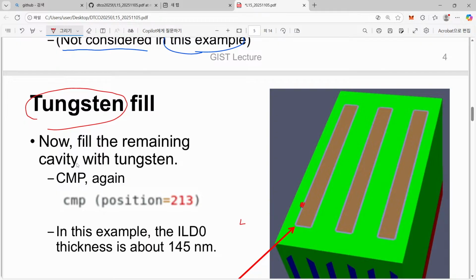Simply speaking, the problem of our nanosheet is related to this. If we introduce a very short channel device, if a gate is so short, then starting from these two side walls, two spacer sides, we will have a growing high K layer, and we have no chance to fill this narrow space with tungsten.